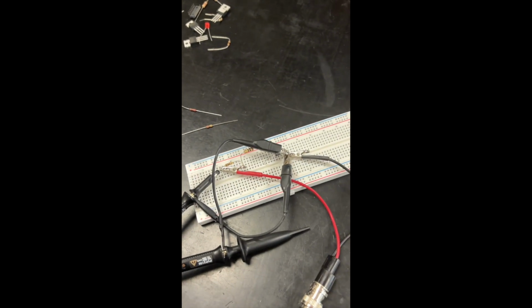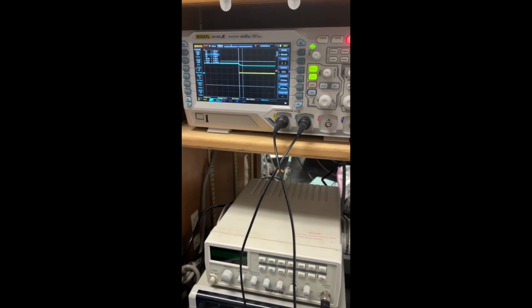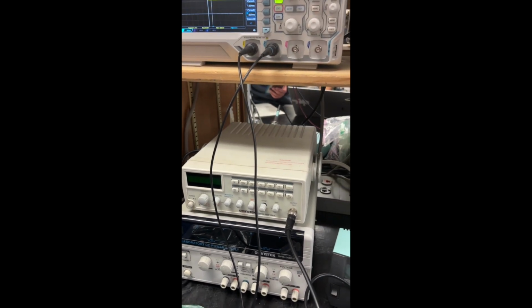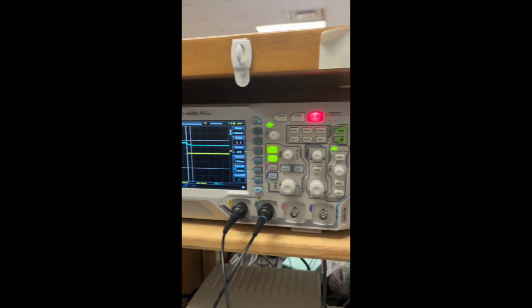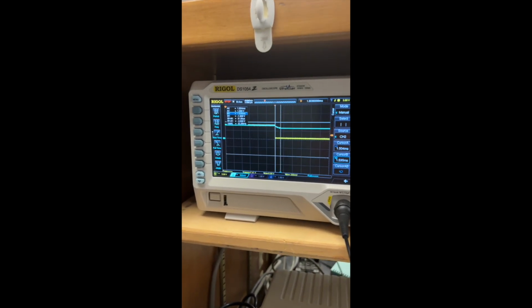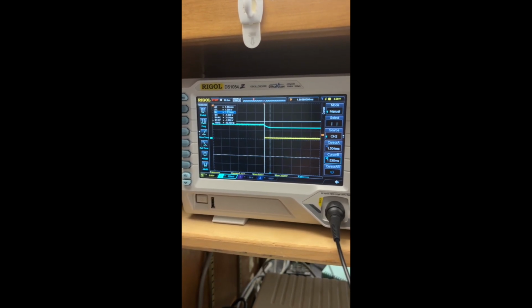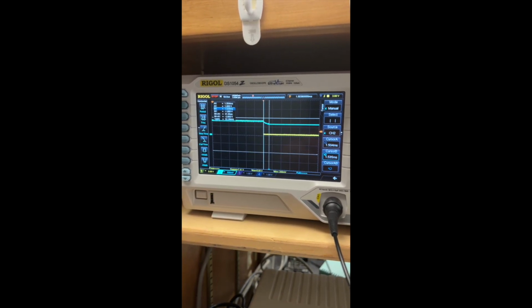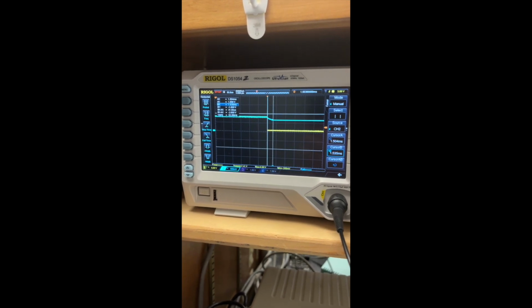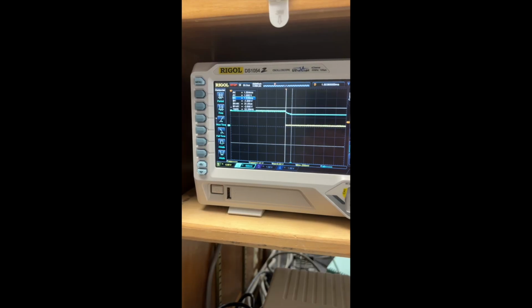Okay, and for exercise 2, we are tasked with using the same circuit, but applying a step voltage of 0 to 9. We currently have it off, but we pause the simulation here to show that the voltage of the diode in the blue drops as a time delay going from one value to the other. And so, using two cursors, we find that that time is 31 microseconds.